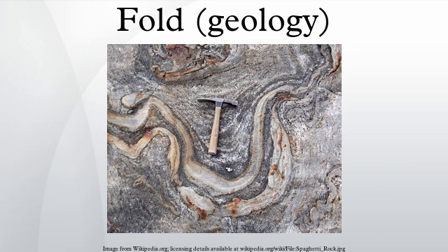Recently deposited sediments are normally mechanically weak and prone to remobilization before they become lithified, leading to folding. To distinguish them from folds of tectonic origin, such structures are called synsedimentary. Slump folding: when slumps form in poorly consolidated sediments they commonly undergo folding, particularly at their leading edges, during their emplacement. The asymmetry of the slump folds can be used to determine paleoslope directions in sequences of sedimentary rocks.